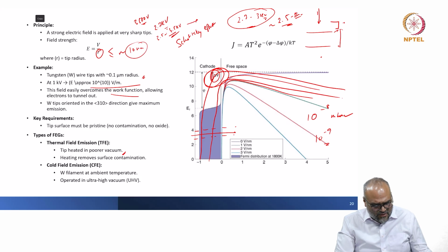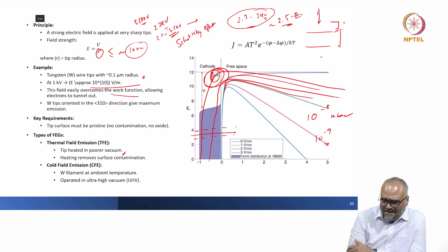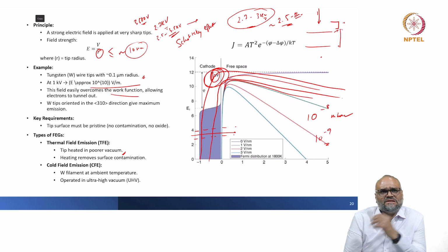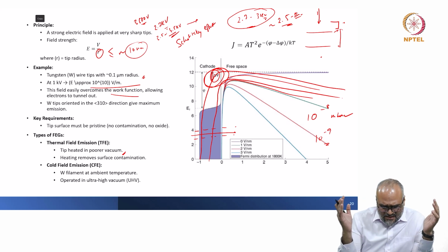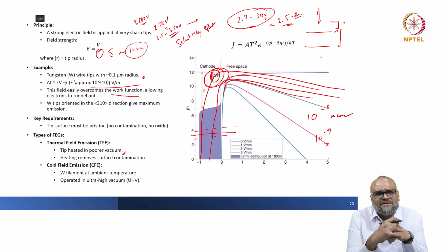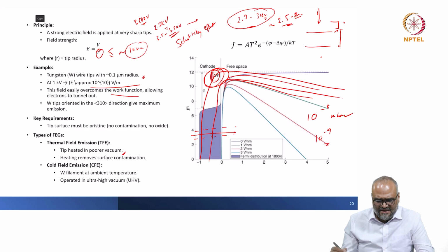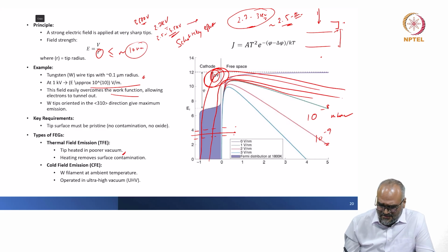And if I look at the other kind of filament, the cold field emitter, I was mentioning that you have to maintain an extremely high vacuum and you want to have tunneling of the electrons. You in fact bring the anode a little closer to the tungsten filament to have an electron tunneling effect, and you do not go past the work function barrier.